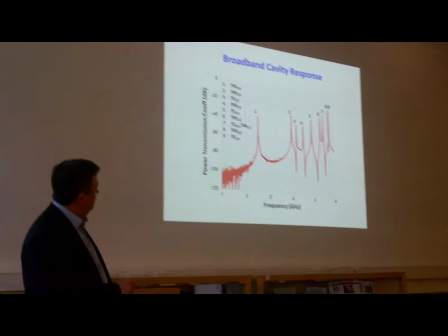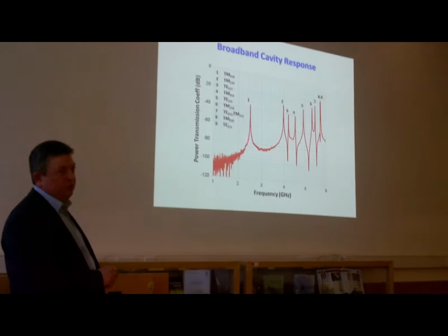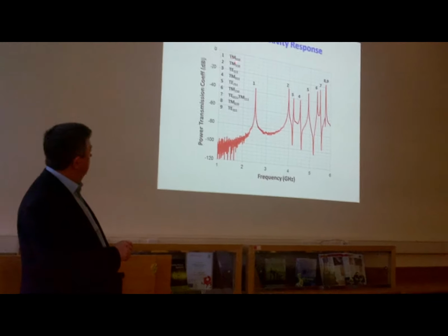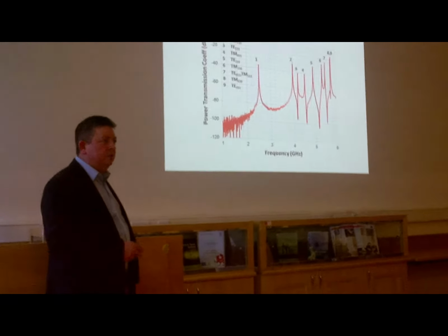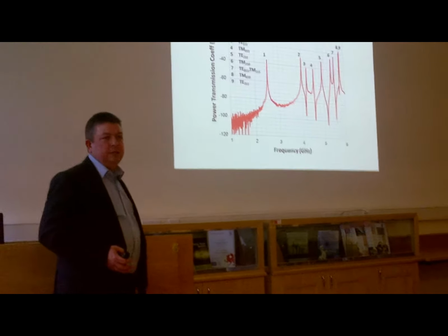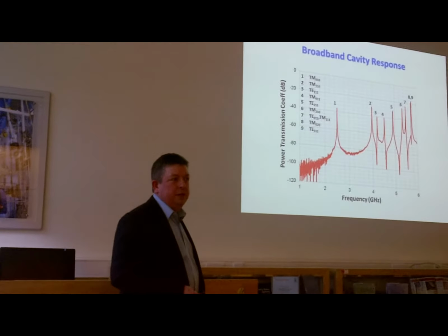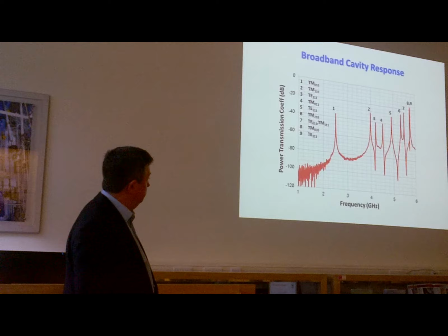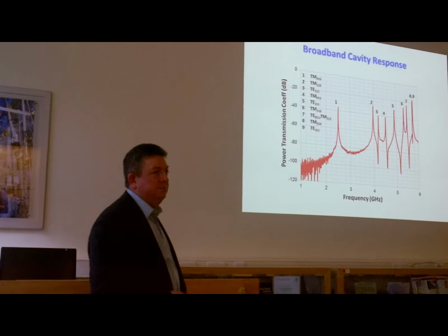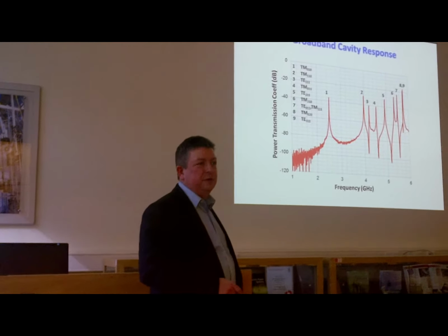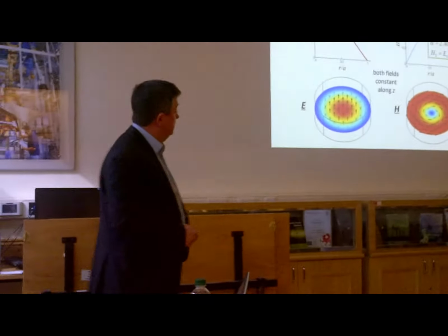Lots of resonant modes of these, so you can catalogue those modes. This is the cylindrical resonator. There's lots of TE and TM modes that some of you may remember from dim and distant electromag lectures. But all of those are quite interesting to us because all of them give you a different field configuration. So we normally design it. So this one is the one, this is the electric field excitation we use. It's the classical TM010 type resonance.